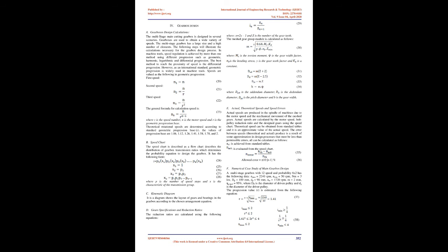Generally, the fourth modification has the highest natural frequency among all modifications, the widest range of natural frequencies, and the minimum value of deformation. These good dynamic results are a result of reinforcement achieved by redistribution and reshaping the structure through stiffener elements added, which play as multiple ribs.